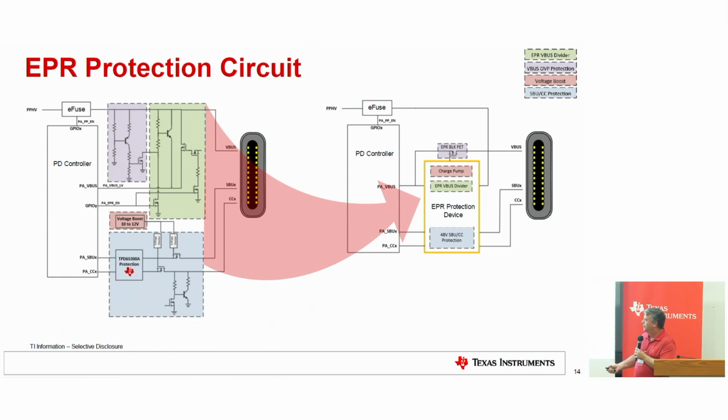One of the key things to think about when you're using it: you'll see the Type-C connector and the cable are really, really small. If the connector starts getting broken or people are wiggling it back and forth side to side, as you see how narrow the pins are, you've got to make sure you don't short one pin to another through the connector.